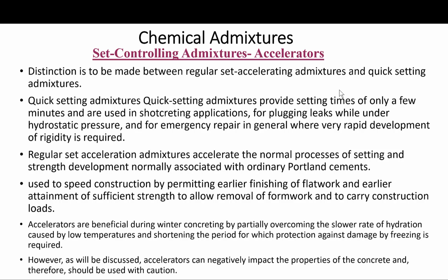The regular accelerators basically are used to speed up construction, by permitting earlier finishing of flat work and earlier attainment of sufficient strength to allow removal of formwork and to carry construction loads. All right.